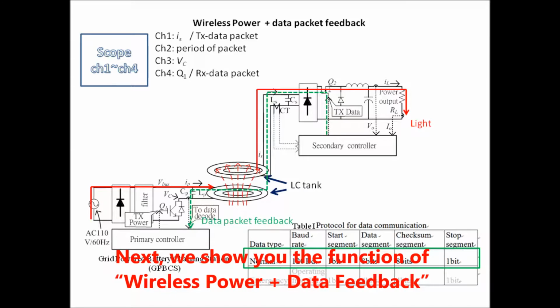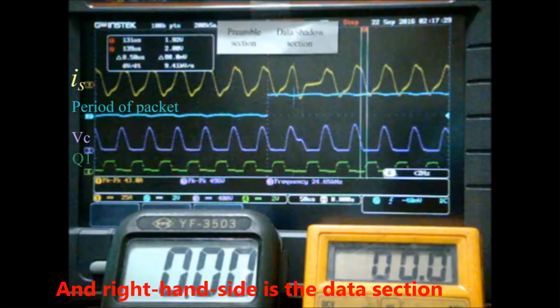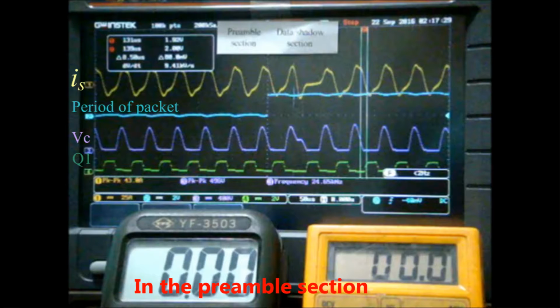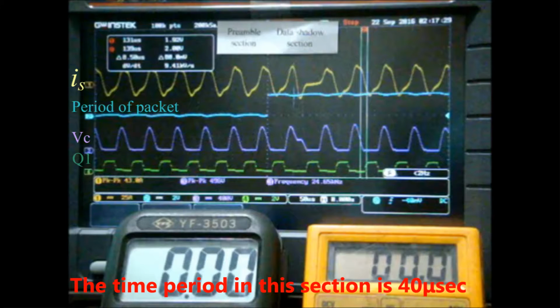Next, we show you the function of wireless power plus data feedback. Here, the left-hand side of the center line is the preamble section, and the right-hand side is the data section. In the preamble section, there are digit 1s without modulation. The time period in this section is 40 microseconds.